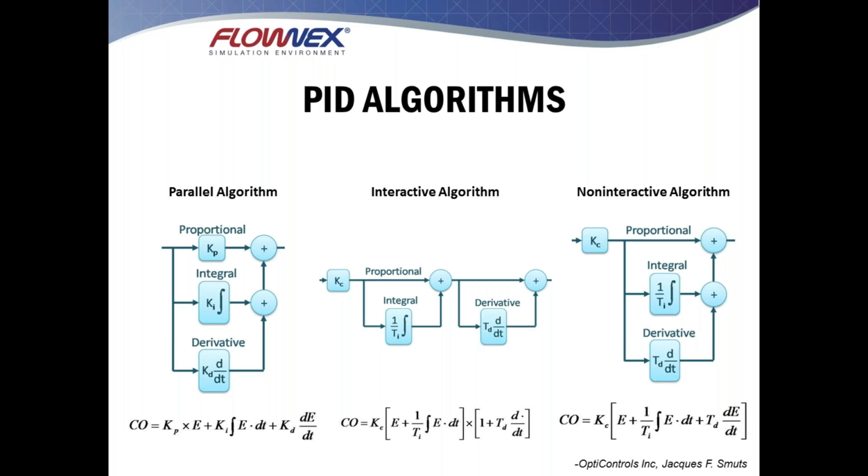The digital control is typically high-level control at the DCS level, where basically decisions are made inside of the control system. This is adjusting ramp rates based on transfer functions, or turning on or turning off systems based on load requirements. It's very much logic structured, Boolean control, if you would call it that. And the other type of control is analog control. This is your PIDs, processors or controllers that receive an analog signal. Based on that, compute a control output. And these controllers themselves need to be tuned.